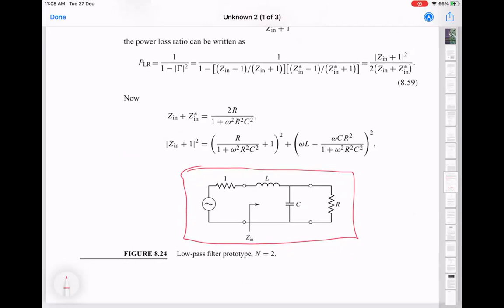So here is an example circuit where you have your source. The source impedance is given as a value 1 because it's just a mathematical simplification that you normalize everything to 1, and then you do the calculation, and then after that you can use some scaling equations to put them to any impedance you like, and similarly any frequencies you like. So you scale the impedances to 1, and you scale the cutoff frequency also to 1. So the omega c is always 1, and then later on this 1 can be moved to wherever you want. So we'll see that in just a little bit.